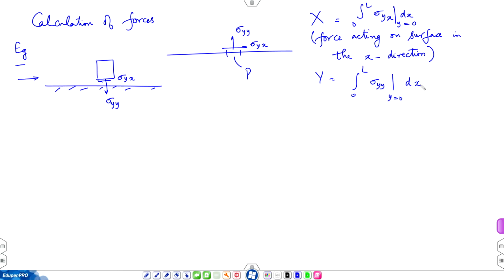Now, Newton's parallel plate experiment gives us a hint that you can find sigma in terms of velocity. So, now let me comment on boundary conditions, that whatever be the velocity field elsewhere away from the surface, at the fluid solid interface, this surface does not allow flow to pass through. So, the normal velocity is 0. So, we are talking about a solid interface where the solid is stationary.